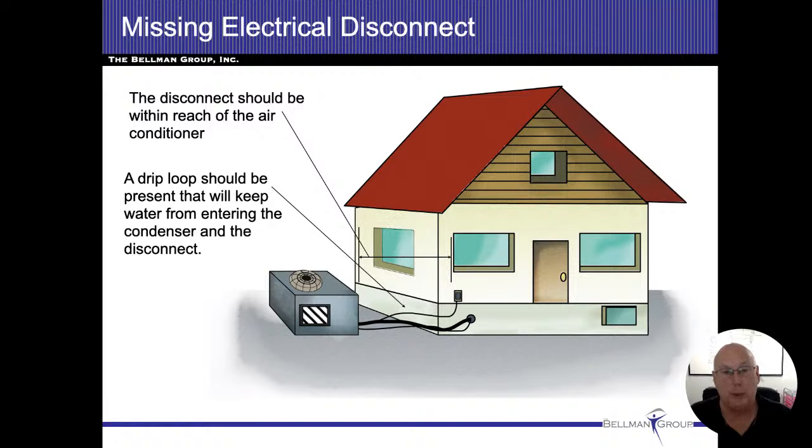It's a good idea to check those connections at both ends. If they're metal, liquid tight, flexible conduit, then we can use the conduit as our grounding system. If the connections are plastic, then we're going to need a separate ground wire that comes through it, so that we can make sure the breaker will trip should we get a ground fault anywhere in the cabinet. All right. So I like to check those connections and make sure that they're nice and tight and secure. And if they're loose, we got a paragraph for that too that we'll put in the report.